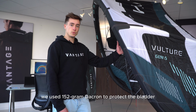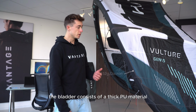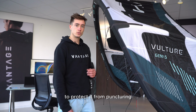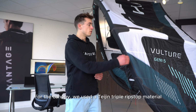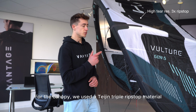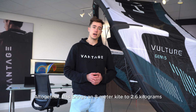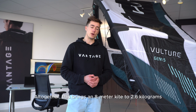For the leading edge, we used a 152 grams dacron to protect the bladder. The bladder consists of a thick PU material to protect it from puncturing. For the canopy, we used a Tigen triple ripstop material with a high tear resistance. This together brings an 8-meter kite to 2.6 kg.